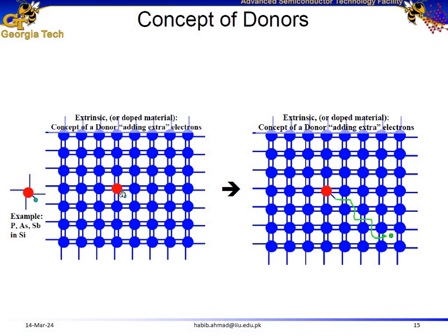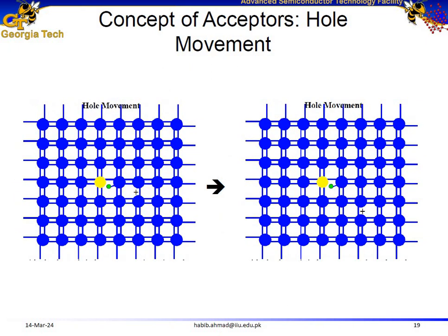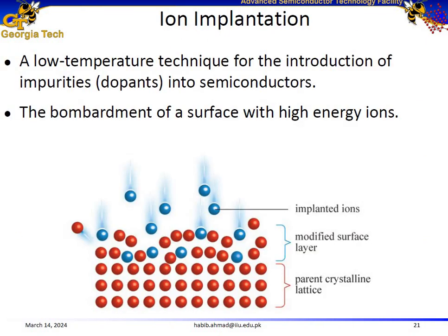In order to donate electrons or holes to the semiconductor, we need these dopant atoms to settle down on proper lattice sites. If they do not sit on the proper lattice sites, they do not contribute electrons or holes to the host semiconductor material. So it's really crucial to activate the dopants. So the first step is to add dopants, and the second step is to activate the dopants inside the semiconductor. And ion implantation also performs the same functionalities.